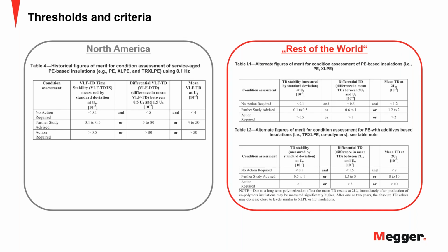All right, thank you. Next is over to Robert. Are there any published criteria available to evaluate remaining service life of aged EPR cables using tan delta testing? The short answer is no. If you think about something like, okay, I collect a certain amount of data, I put it into a model, and it tells you, okay, this cable fails in 2.8 years. That's a clear no. And the reason for that is the behavior of the copolymer cable.